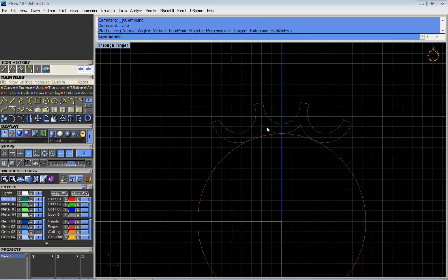All right. Just to make sure that it's a closed line, I'm gonna select all of them and join. You see now here, one closed line. That's alright. That means that I did it right. If I have, for instance, 8 closed lines and 1 open, I should fix it. Basically, it means that I have some open lines. The problem with open lines is that I cannot extrude them. I cannot turn those lines into solids. Okay.